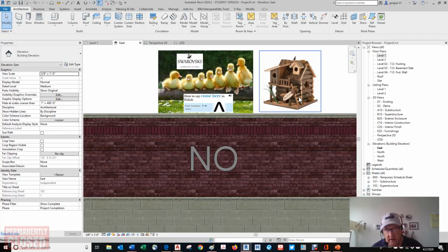We didn't spend enough time on contextual tabs. Contextual tabs are revealed when specific elements are selected or element creation commands are launched. For example, the Modify Walls contextual tab is displayed when a wall is selected. These unique tabs are usually colored green to help you distinguish them from the other static tabs on the ribbon.